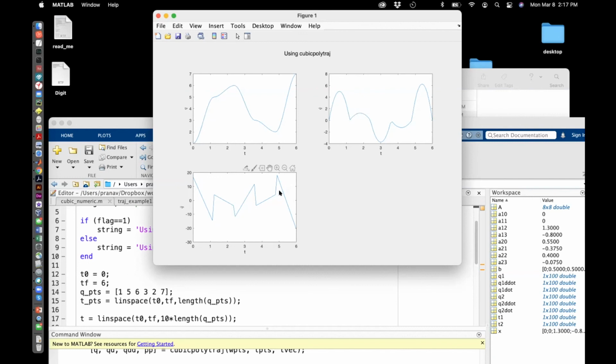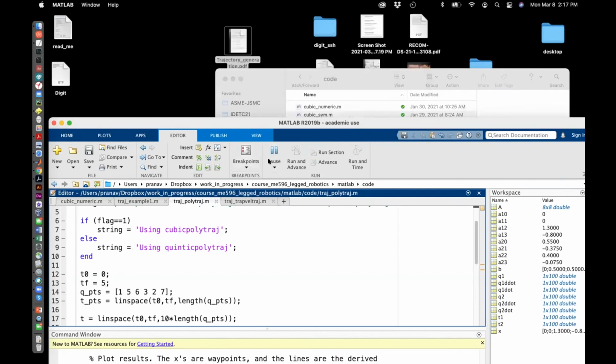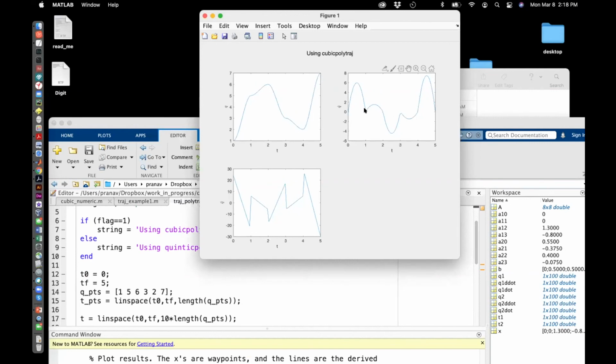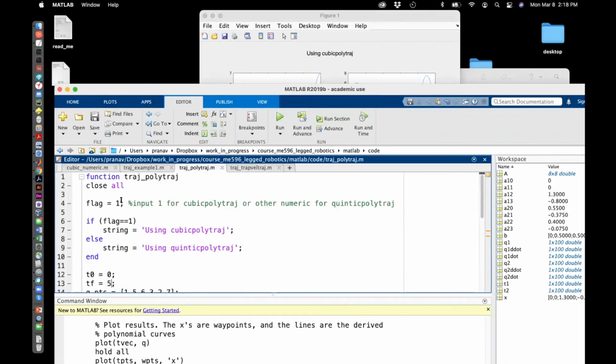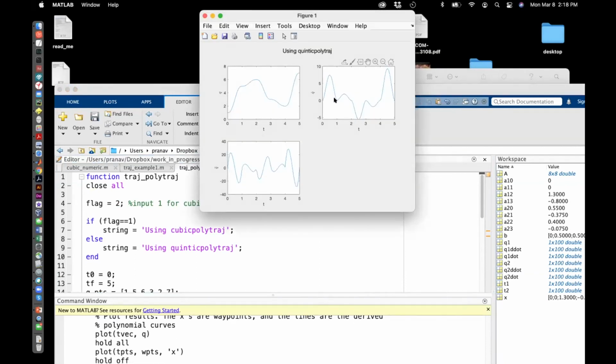So here I did it much easier now because there are 6 things. If you look here, it will actually hit 0 at every second. And this should be 5. Yeah, so now it's right. So here it's 0, and then it should be 0 here somewhere, and then 0 there, and so on. So it basically hits 0 at every single time, which is clearly not what you want. You probably want to specify a non-zero speed. So this is what you get with cubic. If you use quintic, which is 5th order, then you get slightly smoother, but still hits 0.